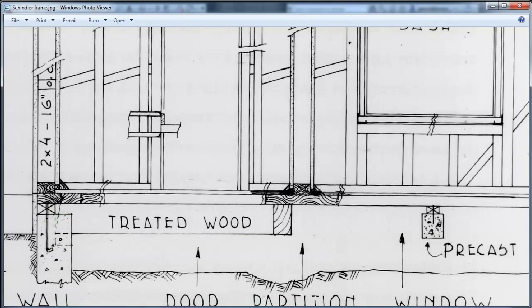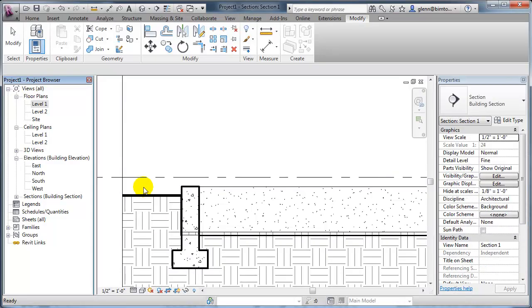So if I pop back over to Revit again, here's what we might do. Okay, we're going to basically do a sweep. It's called an in-place sweep because we're going to follow some existing geometry. And what we're going to do is actually just develop a profile. And in terms of that profile, I can sort of be sneaky about this. I just need a rectangular box that's like 3.5 wide by 1.5 tall. And I could create one that's specifically for that.